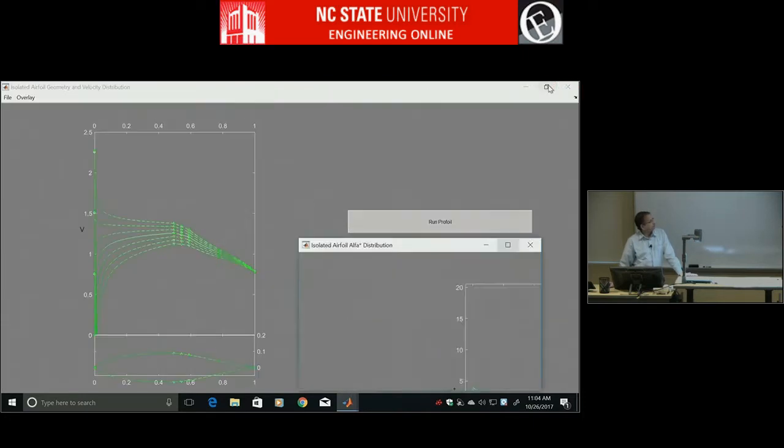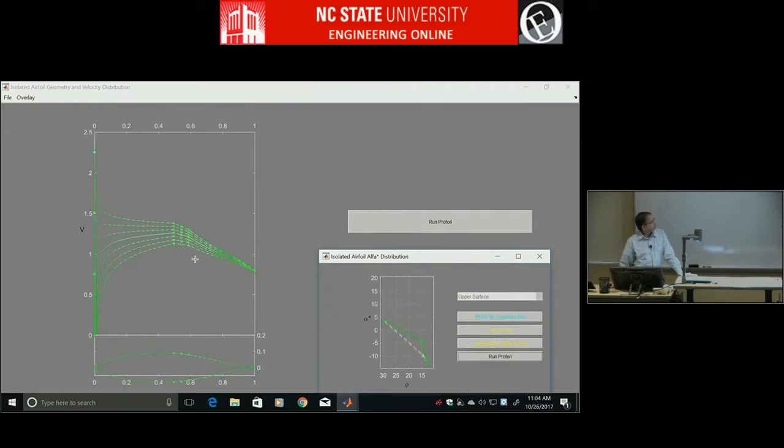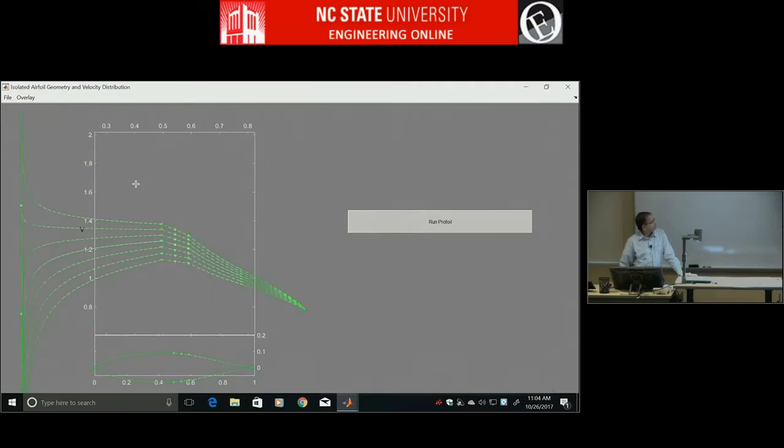What you have to think about is velocity distribution. Now you can see the velocity distribution, it's more rounded, right? So it's favorable, little bit adverse, more adverse, and then it's got that. And you can keep going a little bit more. If you want, you can insert one more segment here and make this even more rounded.